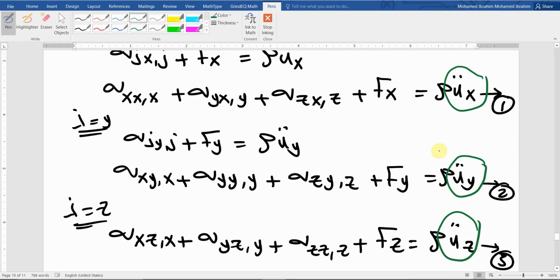So that's why we end up with just three equations of motion to describe the 3 degrees of freedom of the particle that belongs to the continuum. Make sense? Everything is related. The mechanics of the particle is related to the mechanics of the continuum. And again, in classical mechanics, we assume the particle as a point. A point has only the degrees of freedom to move along x, y, and z. So that's why the equation of motion in classical mechanics is only 3 equations.